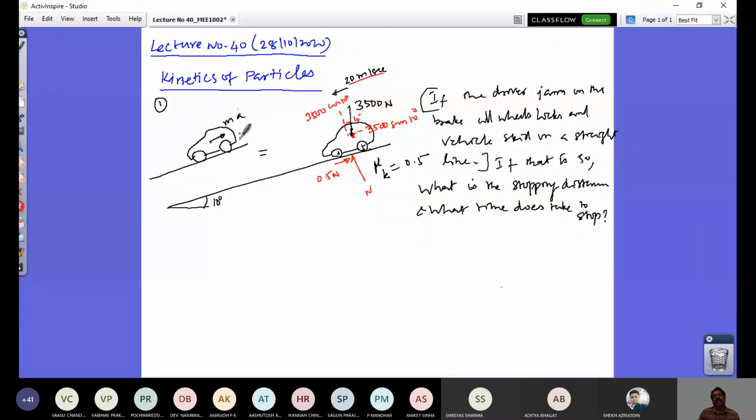So if this is the braking force here, on the other side it would be the inertia force in the same direction. So because of this free body diagram, this side is sigma F, and this side it is MA, right? So you can now find out what this deceleration rate is. Just let us work out, write the equation along the vertical direction, find your, 1 minute.